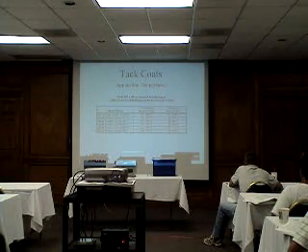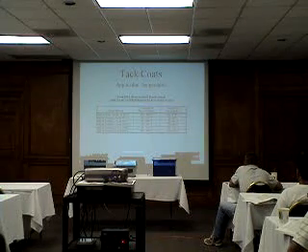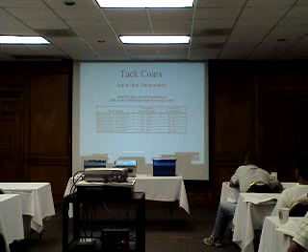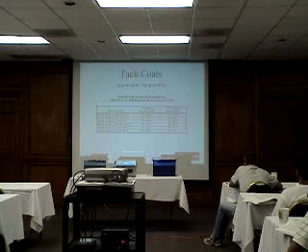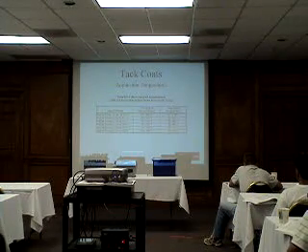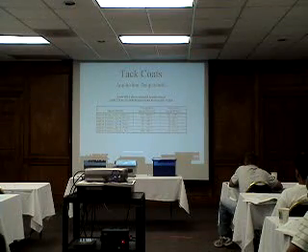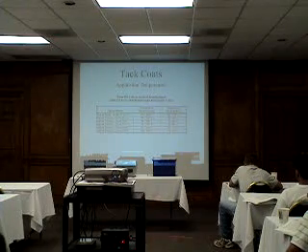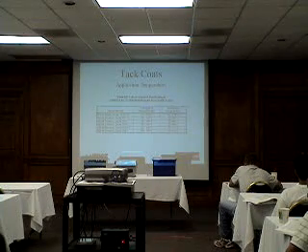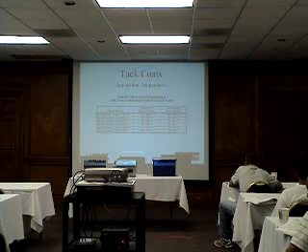I tell you that. These others, you're talking about somewhere in the 120, 130 degree range. It's still hot, it will still burn you, but it's not as bad as something that's going to be about 400 degrees. So the contractor will be allowed to choose any one of these emulsions at this location here, unless there's some divisions which in their contracts specify the use of PG 64-22.